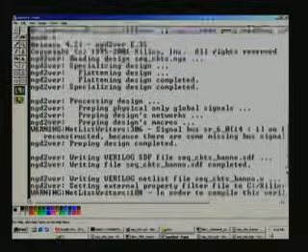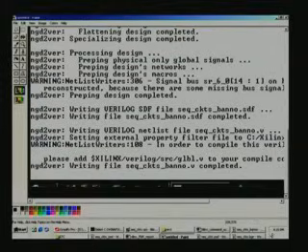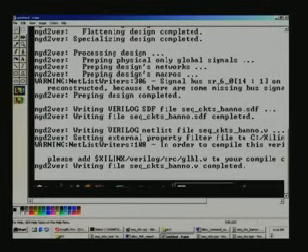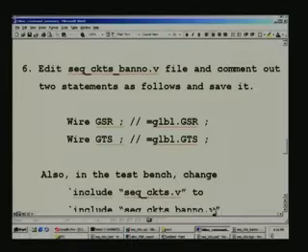And so finally, an SDF file is created here, it says writing into that, and that is completed, and then a Verilog netlist, that is .v. This is the file which we need, is created here, and once again some warning is given here, and finally it says it is completed. It is only reminding of some procedure. So this warning is not a serious thing. So now what we will do is, we will go back to the summary and continue from where we left.